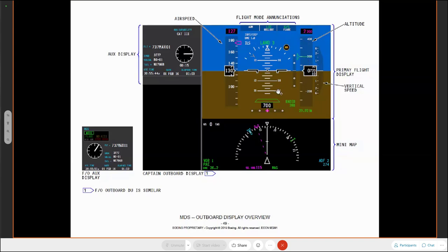If your airline or the aircraft you're working with has their rad alt up here in the top right hand side, I would guess on the MAX they'll have it there as well. This is what they class as a rising runway, and again this is optional. As the aircraft starts to descend below 200 feet radio altitude, this green box starts to come up. It's basically showing you where your aircraft is relative to the runway itself, what they call a rising runway.